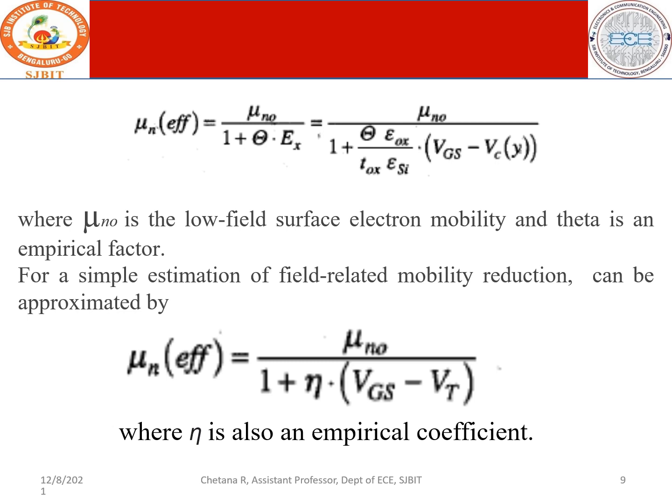So whenever the short channel is considered, the length varies, as a result the mobility varies, as a result the current varies, and the whole of the electric field is going to change. That in turn has an impact on the mobility and the current flow.